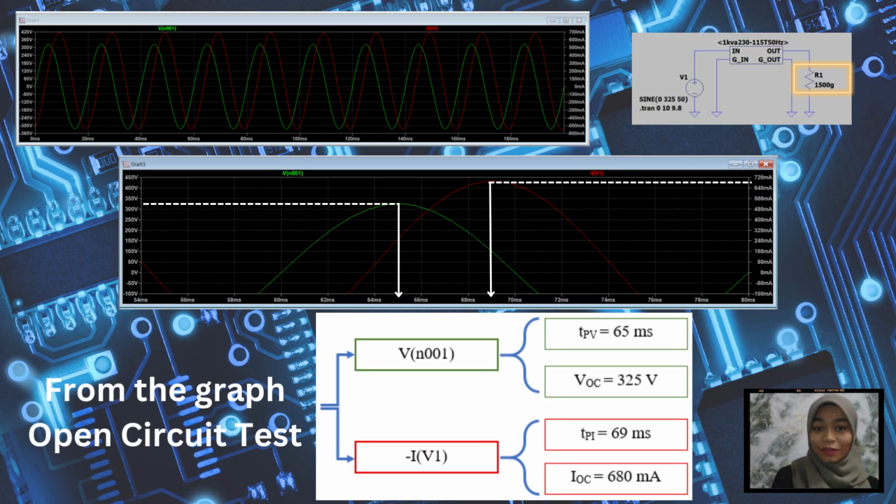From the open circuit test graph, two graphs were plotted. From the voltage graph, we obtain the time of the peak voltage TPV equal to 65 milliseconds, and the voltage of the open circuit VOC equal to 325 volts. From the negative current graph, we obtain the time of the peak current TPI equal to 69 milliseconds, and the current of the open circuit IOC equal to 680 milliamperes.